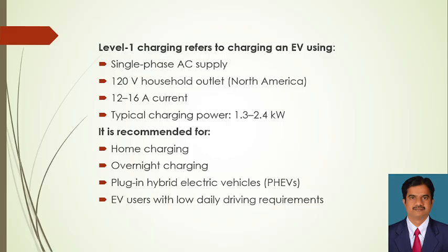So level 1 charging refers to charging the EV using a single phase supply, a 120 volts household outlet. As I said, 12 to 16 ampere current, and typical charging is less than 3 kilowatt. Level 1 charging is recommended for home charging, overnight charging, plug-in hybrid electric vehicles, and EV users with low daily driving requirements.